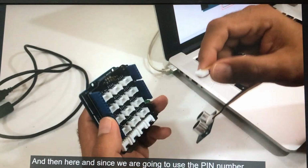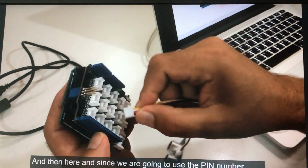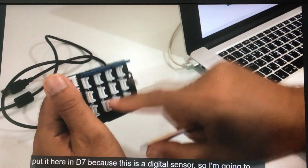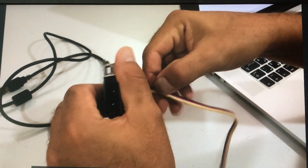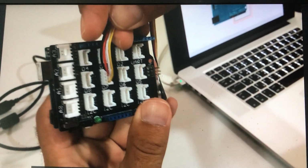And since we are going to use pin number 7 of the connection, I'm going to put it here in D7, because this is a digital sensor. You can see that the yellow wire corresponds to D7.